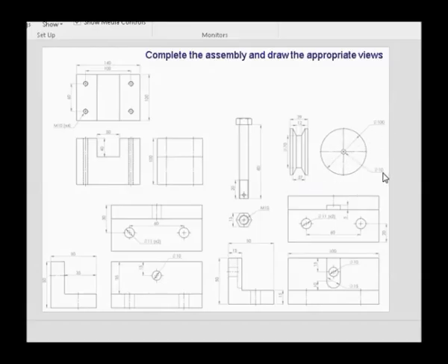It's got a diameter of 100, inside diameter of 10, width of 39 on the outside, and then the V profile is given by these dimensions. Bottom left we've got three views of an L-shaped component. It's 15 wide over there. The bottom is also 15 high. I get the 15 from 50 minus 35.